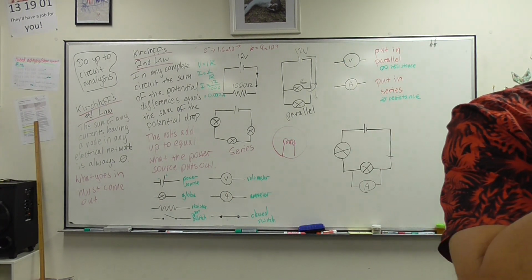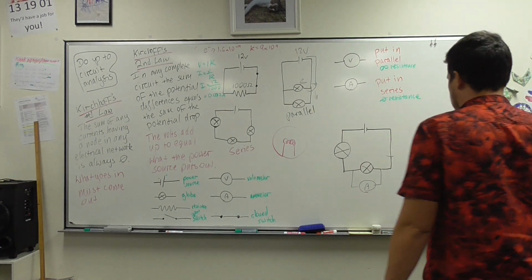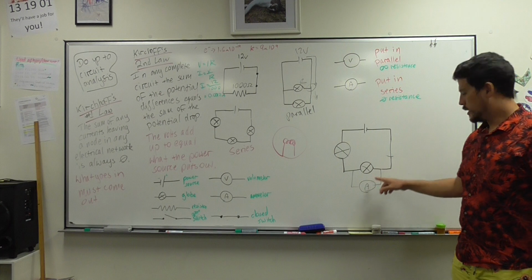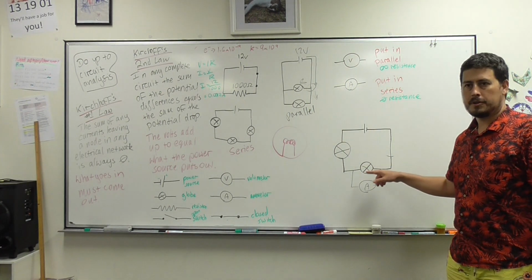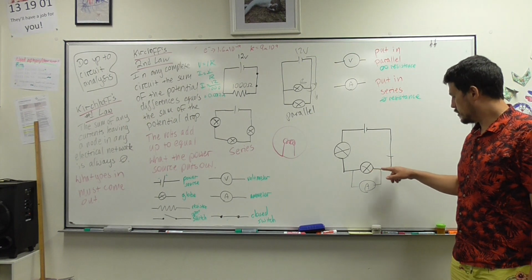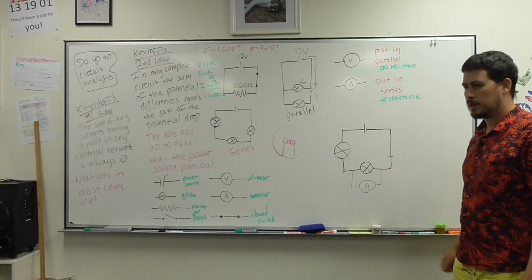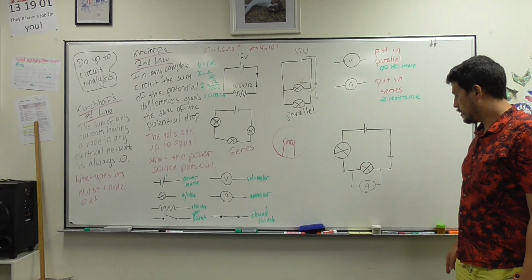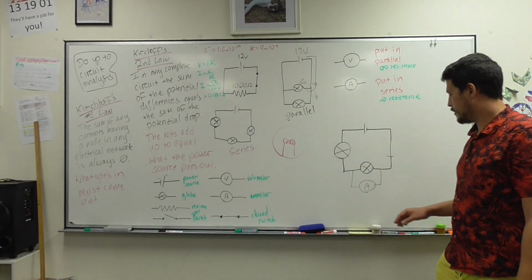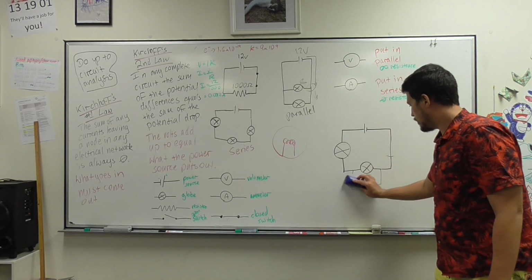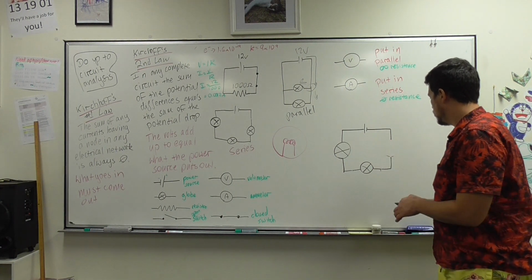Electricity always chooses the path of? If you provide a path of least resistance, like an ammeter, it's going to go, woohoo, I don't have to get forced through this tungsten filament globe and heat up. It's going to go through the ammeter, because there's no resistance. So you've short-circuited with the ammeter. The problem with that is, you're probably going to find that it will dump a bunch of load across the ammeter and burn it out. So you never put the ammeter in parallel. You always put it in series.